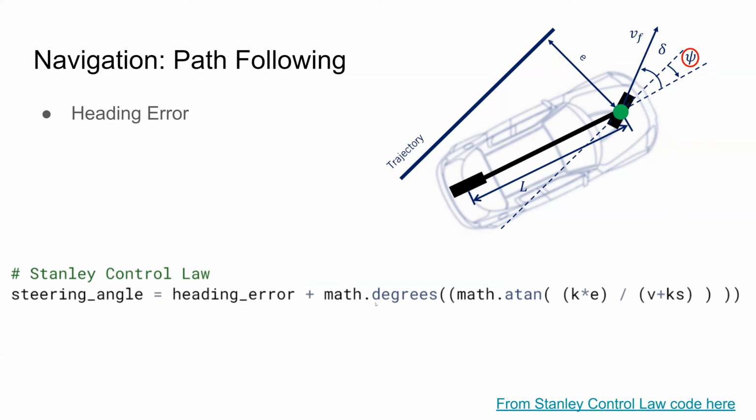So if you need your final value in degrees, like for us, we needed our steering angle to be in degrees because that angle would be fed into our servo, which only accepts degrees, you just have to make sure you keep that same standard of units. And so we used this degree converter to get that. I uploaded our code right here, and it's in our ASME drive.